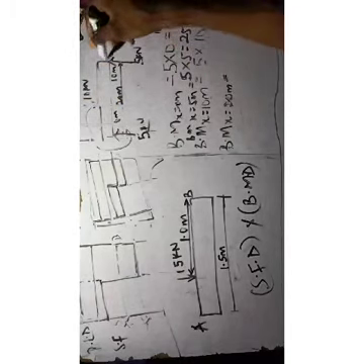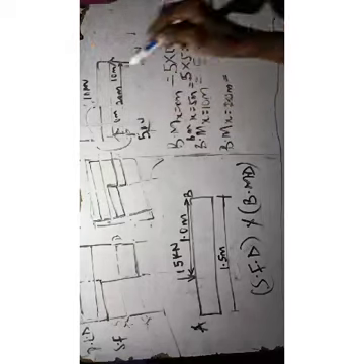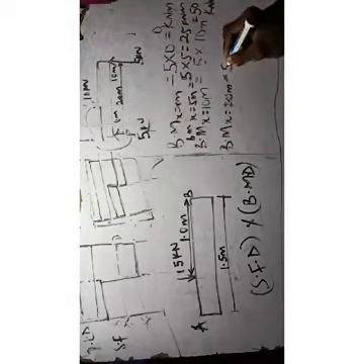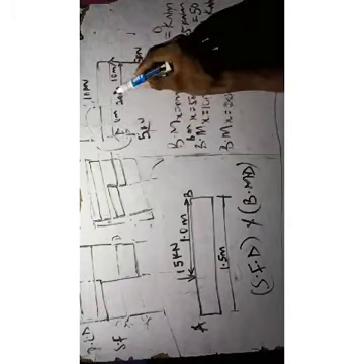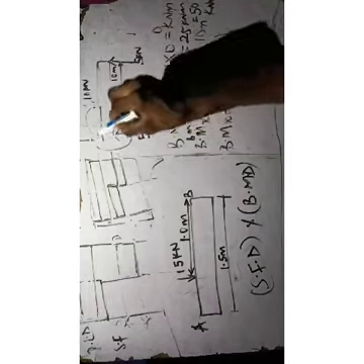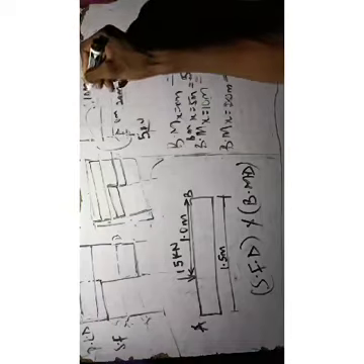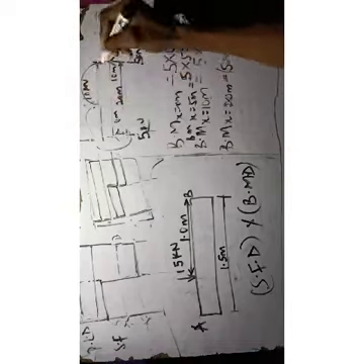You find out it is the same thing. So when you find my bending moment here, the total distance covered is 5 times 20. This force is covering the total distance, that is 20. Also, if I cut it here, this 10 kilonewton is covering the distance here, which is 10. That'll be 5 times 20. Don't forget this is clockwise and anticlockwise. That'll be 5 times 20, covering the total distance.